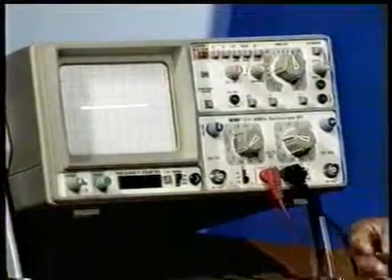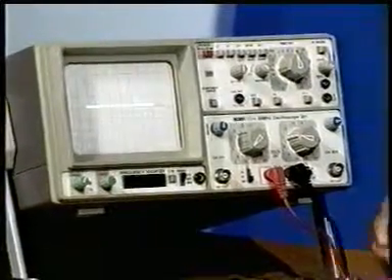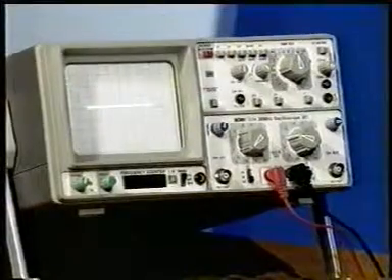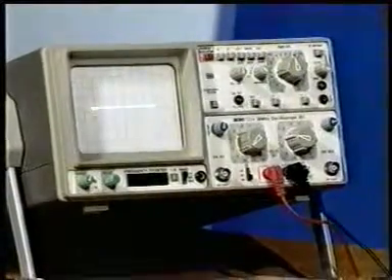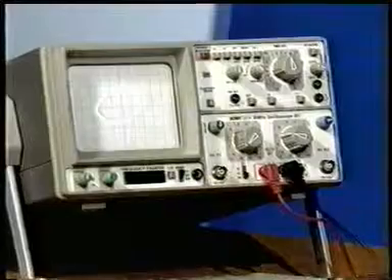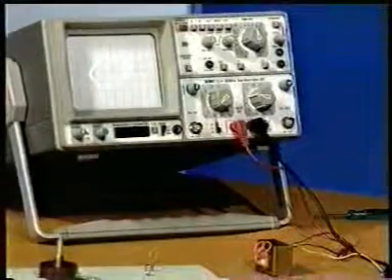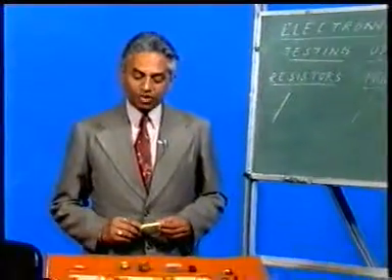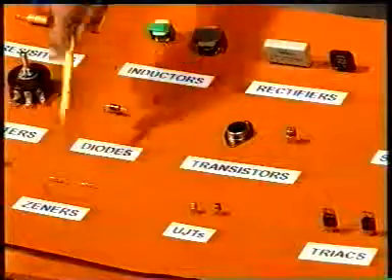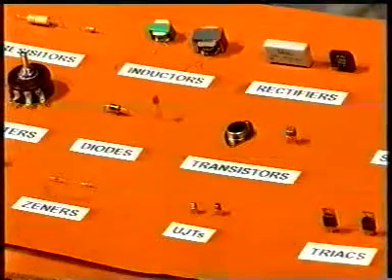The inductor, of course, in place of an inductor we are going to show a miniature transformer. We are going to use it as an inductor coil, and when connected, this loop is coming on the CRO screen, and this shows that the inductor coil is healthy. Fine. Thank you. So after taking up the resistors, the potentiometers and the capacitors, we are now going to take up the diodes, Zeners and the rectifiers.